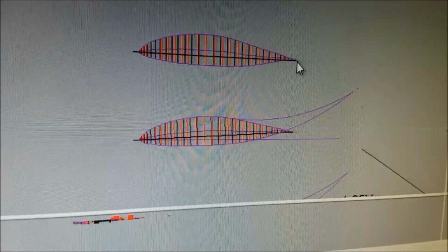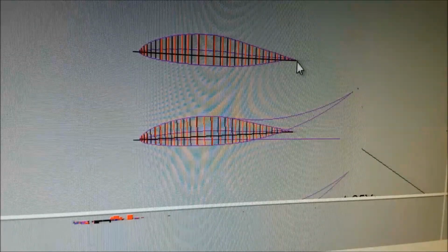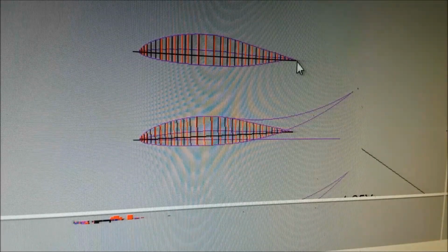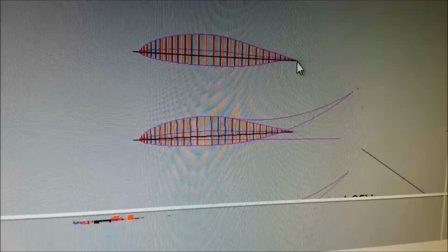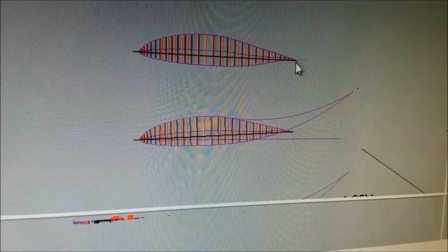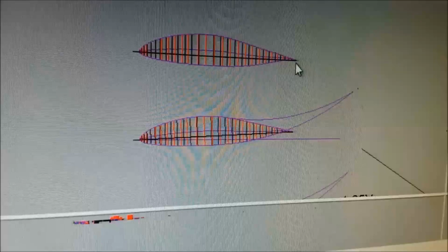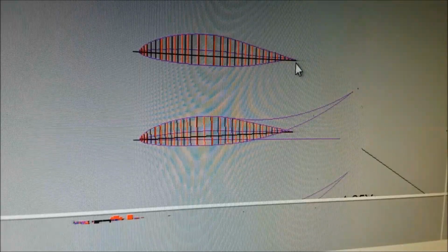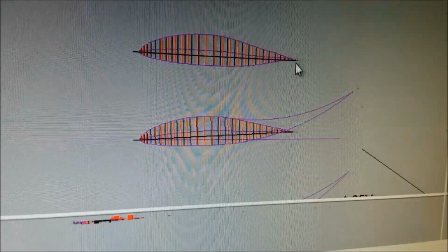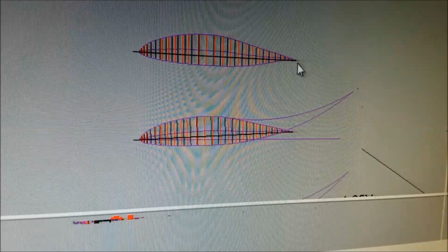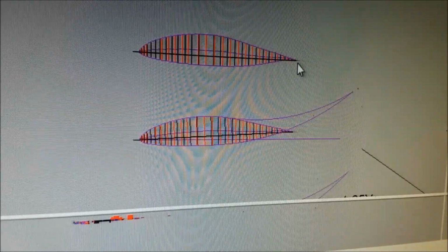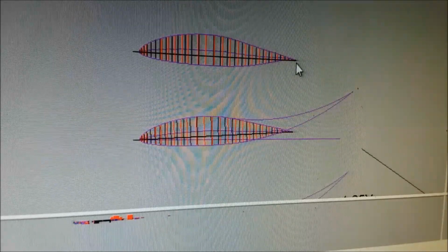You want to cut that when it's still half green. You can touch it. You can't leave fingerprints in it. You can bend it a little bit, but it's not the least bit sticky. It's sort of like rubber. They call it the rubber state. And you can put a straight edge up there and just cut it with a